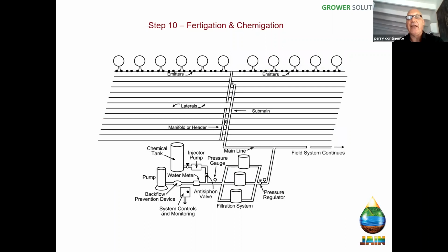So again, with fertigation, have a strategy for fertigation. As a general rule, I always advocate putting the fertilizer injector upstream of the filters and turning it off when we flush. But you should have ports on both sides, because there are going to be some materials that can't go through the filters for whatever reason, and also acid injection.